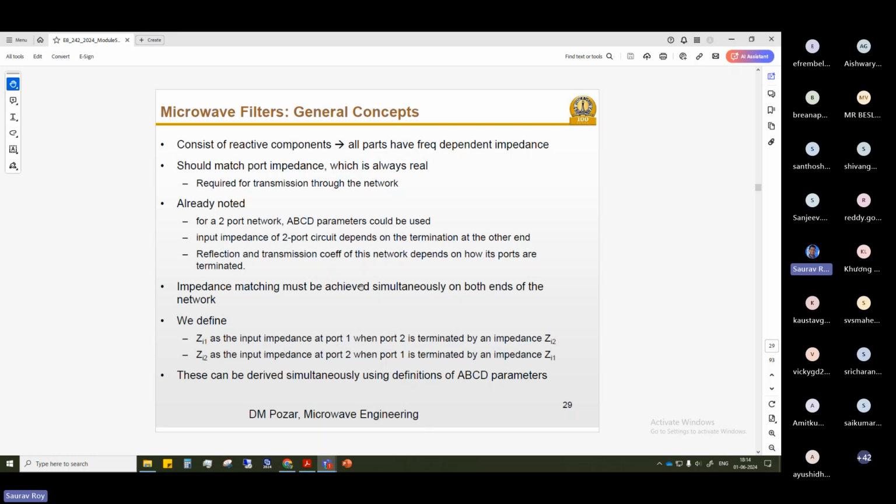Microwave filters based on microstrip line. And for most frequencies, unless you go to very high frequencies, it will work. So that is what we'll do. And if some of you might be interested in millimeter wave, there you have to use either SIW line or CPW line. But the theory again remains the same. How you implement them is different, but the theory remains the same. So here in this course, we'll be covering microstrip line only. And as you know, it works very fine up to several gigahertz.